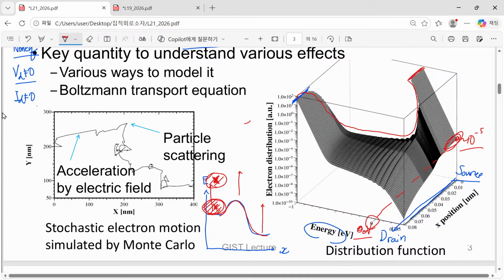Therefore the minimum energy in the source point and drain point is much different, and this reduction in our scale is corresponding to Q times VD. By applying a certain drain voltage, we can pull down our minimum energy at the drain side, and that is corresponding to the energetic location of this point.